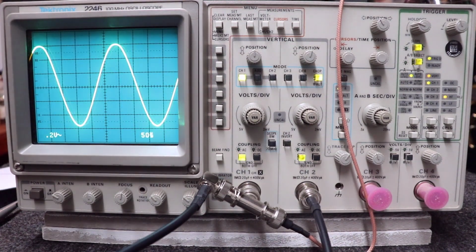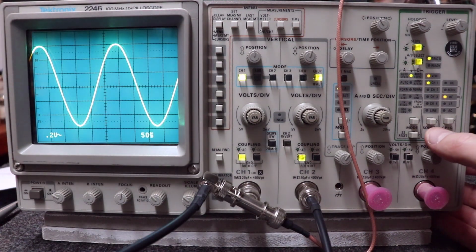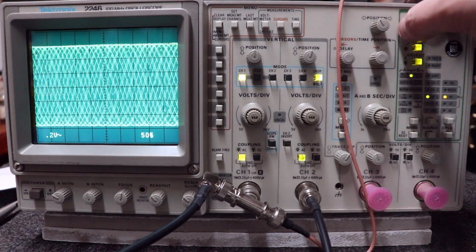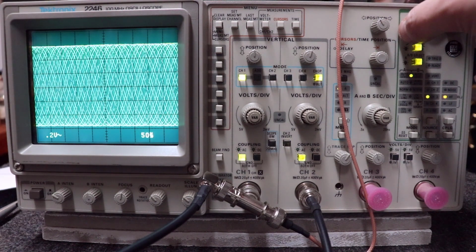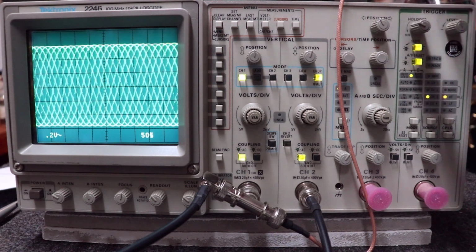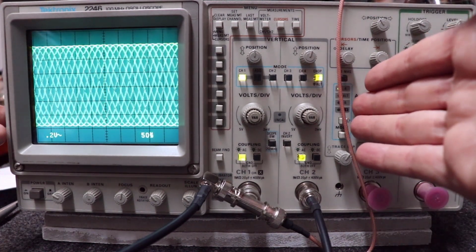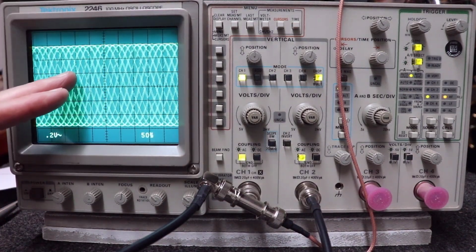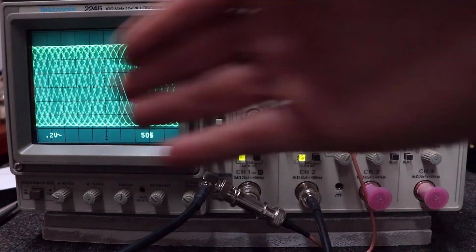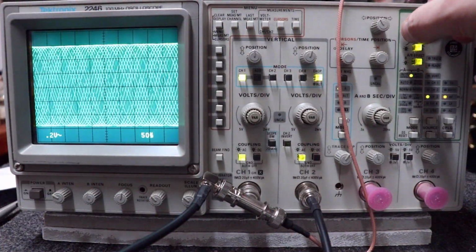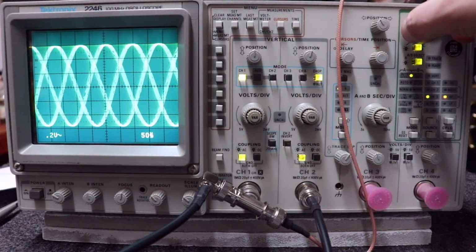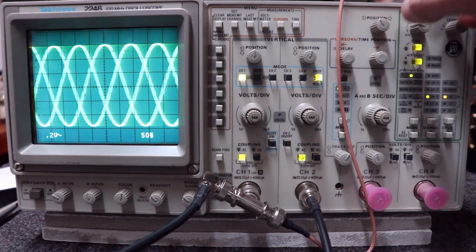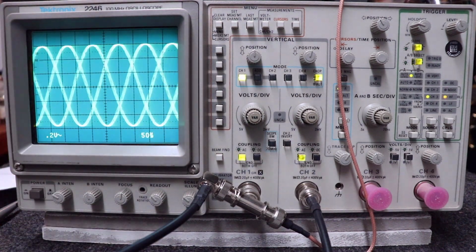And you say, well, what the heck is triggering? Let me give you an example. This is an untriggered signal. In other words, it's not locked on to that sine wave. The oscilloscope's time base has to get in sync with the signal's sine base. Otherwise, your signal is constantly scrolling one direction or another and not locked in, so it doesn't show your repeating sine wave over and over.